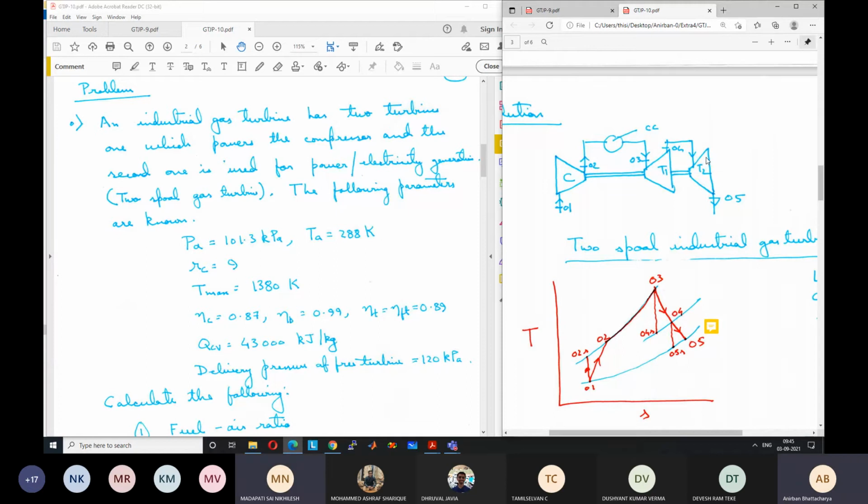Yes, sir. Yes, because you need more cross-sectional area. Because the length of the blades is higher, if you rotate them at the same speed as the first turbine, this second turbine is actually limiting the design. Your stresses depend on the length of the blade and also the tip velocity. Tip velocity is very high, right? If the length of the blade is larger, the tip is rotating at a higher speed. If the angular velocity is the same, the linear velocity is higher, right?